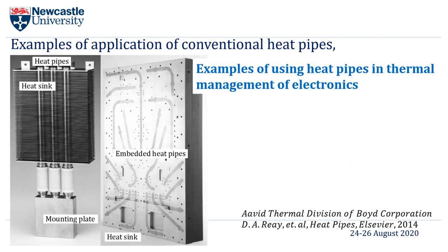A typical application of the heat pipe is shown in the next slide. On the left we have the usual arrangement: mounting plate, heat pipes, and heat sink. You might have seen something like that before. This is maybe something less usual, where the heat pipes are embedded in the cold plate, where there are various mounting places for various components, and that allows nice heat transport to the periphery of the plate, where there are heatsink features attached to such a plate.